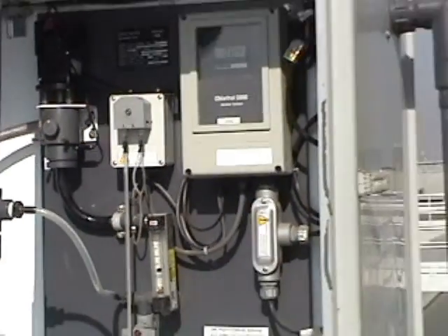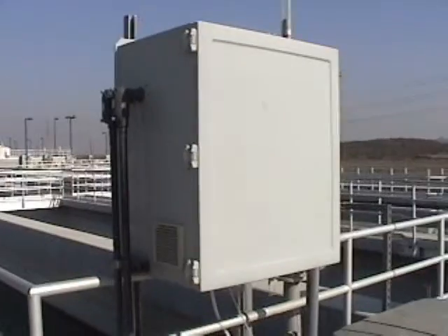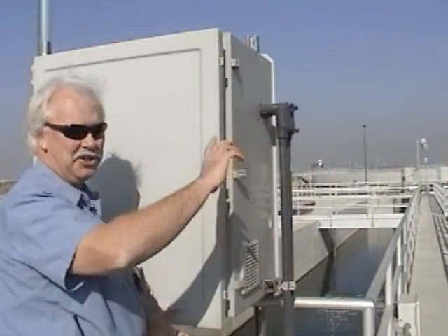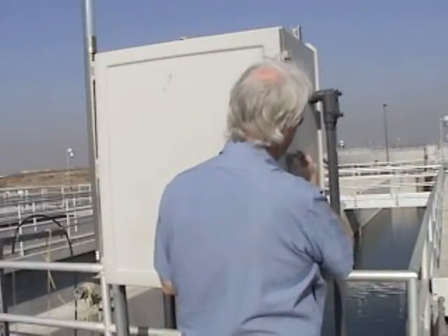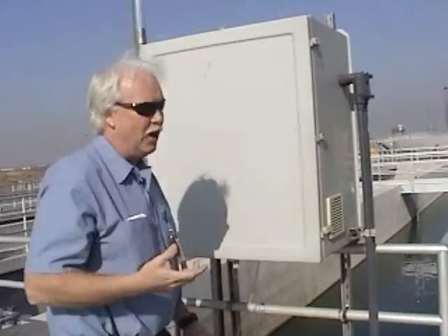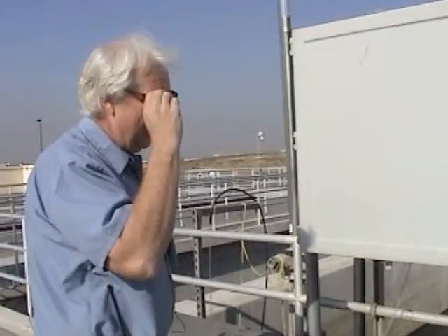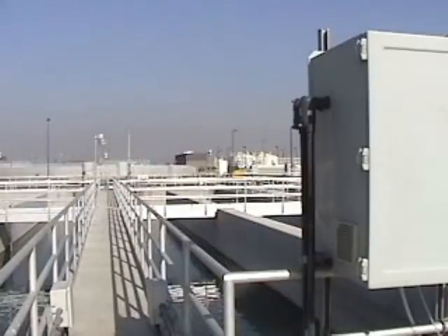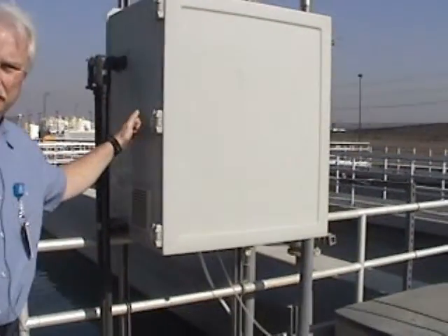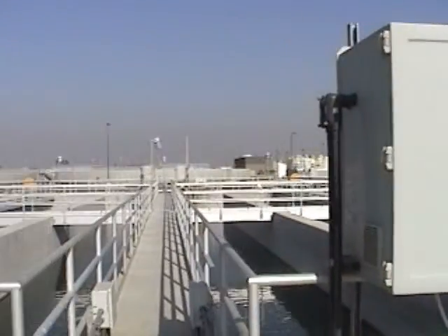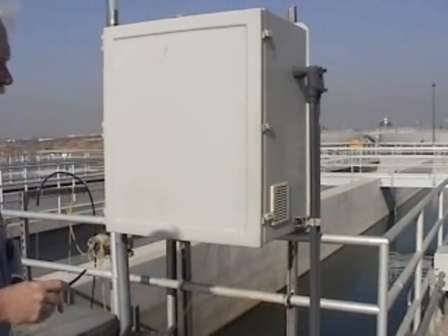What's nice about the system is if this analyzer were to fail, you can control the plant off of that analyzer or vice versa. You can log in if you're on call and it's the middle of the night, and suddenly your effluent residual goes very low. One of the first things I would do from the laptop is switch analyzers. And you'll be able to tell too, if this is reading like 0 and you've got a residual of 5 over here, what I would do is switch on to this analyzer and check out what happens after that.